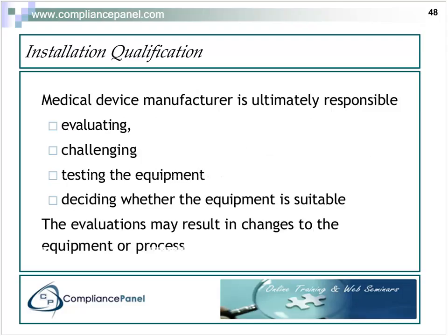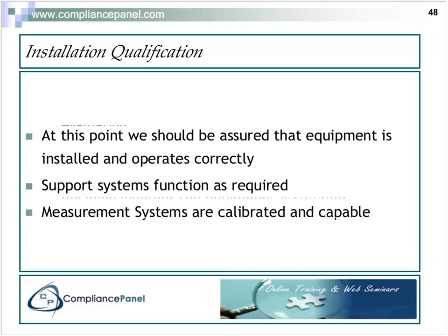We are ultimately responsible as a medical device manufacturer for evaluating the IQ, challenging the equipment, that is, testing it over a wide range of its capabilities, and deciding whether the equipment is suitable or not. And we may have to make some changes to the equipment or the process as a result of this. So at the end of IQ, we need to make sure that the equipment is installed and operates correctly and that the support systems function as required.